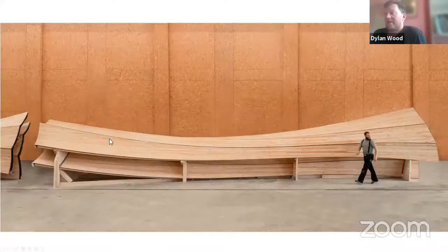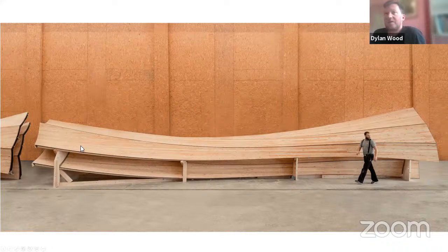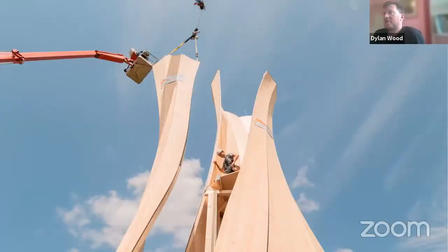Then after these are manufactured, the components are combined in groups of 3, and a weatherproofing membrane is added along with a larchwood glue laminated facade to protect the structure from water. And then these are transported to the site in groups of 3 or 6. And then on the site, it takes only a couple of hours for the workers to assemble them into the tower structure by basically inserting screws into the pre-drilled holes after each group is lifted up into place.